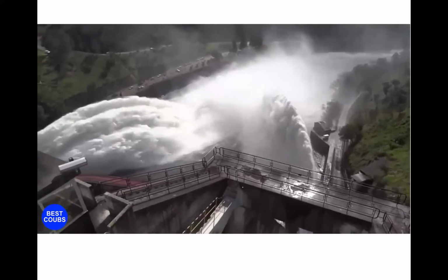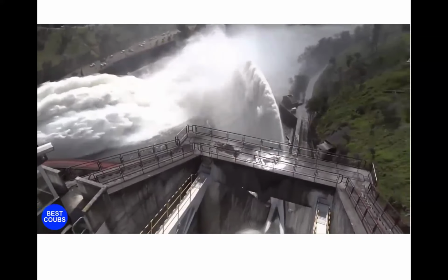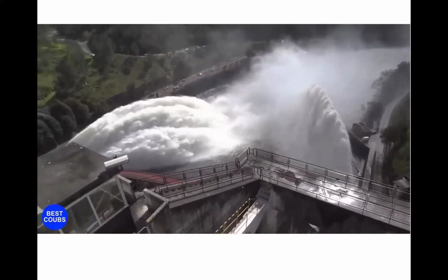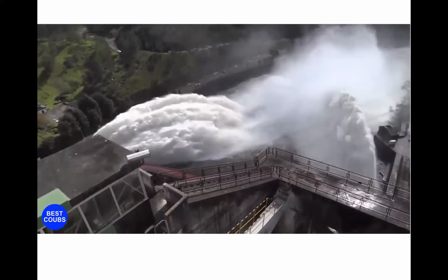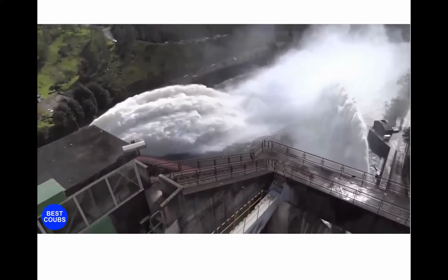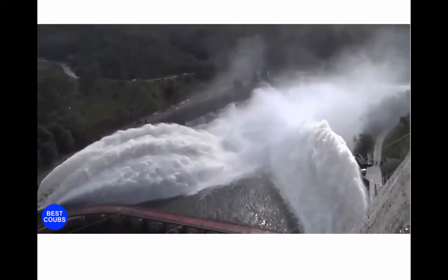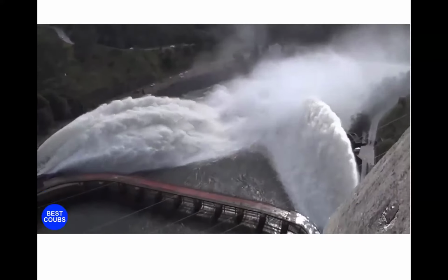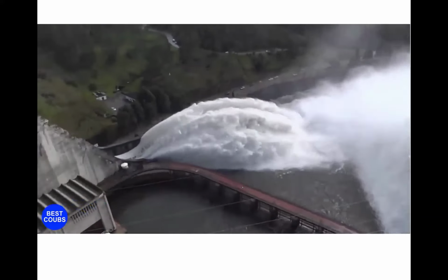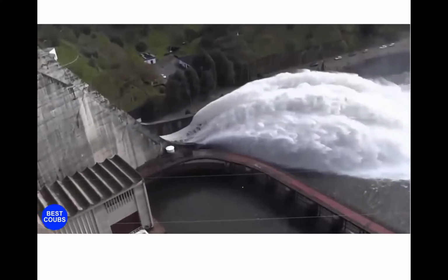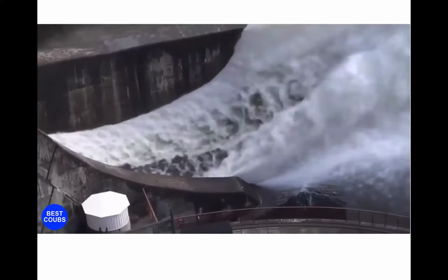And I think we keep talking about supercritical flow being a hazard in terms of erosion. I think that's a good way to visualize what we mean. This kind of flow, if you leave it alone, can erode everything downstream. So we have to manage it. Another view of a flip bucket type spillway. And all the white water that you see is in a way a good sign. It means that the water is breaking into smaller and smaller drops and dissipating and losing most of its kinetic energy.